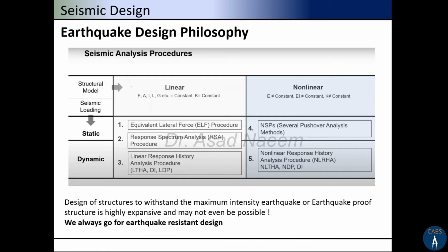Even if you provide a large amount of force on a building structure, it will give you a large displacement, but this will be unrealistic in the case of an earthquake, because there is a certain limit at which the building can bear the forces and displacement. It has to be restricted at a certain point where it will definitely have some cracking and collapse. But this phenomenon is not shown in the linear model.